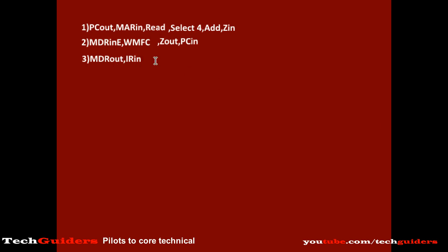Now the instruction is fetched to the instruction register. It will be decoded by the decoder and the control circuit. We have two operands, one operand from the memory, other operand in the general purpose register R0. To fetch the operand from the memory, the address of the operand will be loaded to the memory address register. At the same time, a read control signal will be issued by the control unit to the external control bus. Now the address becomes available on the external address bus,